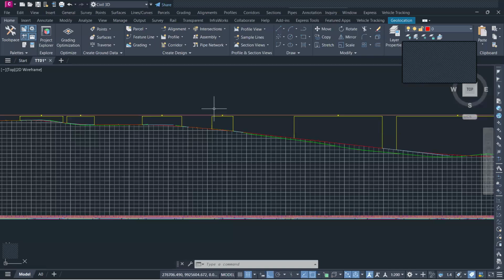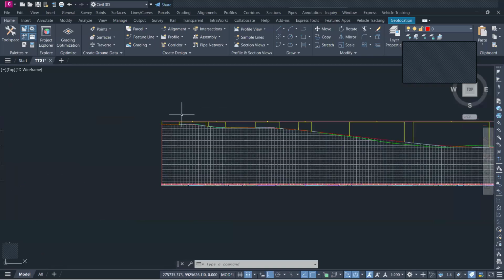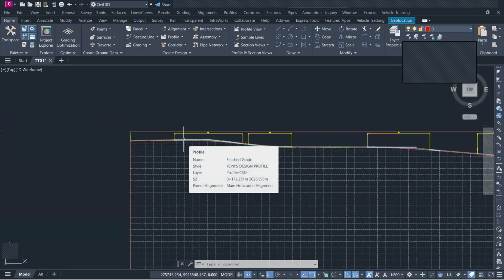So while you are the design engineer, and as you will be going out there, one of the critical things is making sure that your surveying equipment is calibrated, and that your benchmarks are well secured. You cast them using concrete and an iron pin, and you make sure that you have a good base that will not be moved.